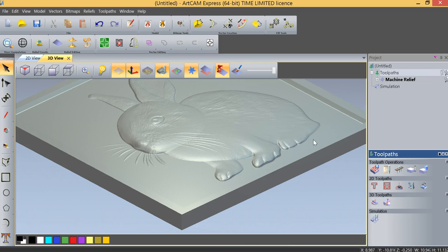So now I have two choices. We can take that DAT file, load it straight to our thumb drive, put it on our machine and run it. As those of you who have done any output files on your machine, which I'm sure you probably have, you'll know that there is no border function with that DAT file. If you want to make sure that you have that border function and it's active, then you need to take that DAT file into iPicture, convert it to a G file, and we've gone through that operation in several of the previous videos, so we won't go through that again.